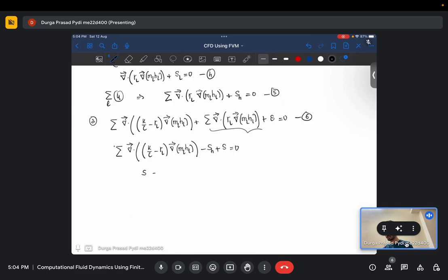So we have the source term as SH, where SH is the summation of all the individual generation terms for all the species, and we also have divergence of gamma L minus K by C times grad ml times HL. So this is how the overall generation of enthalpy is related to the species individual generation enthalpies. So essentially the first term is the generation enthalpy for that particular species, and this is essentially because of the non-homogeneity of the species distribution inside our volume.